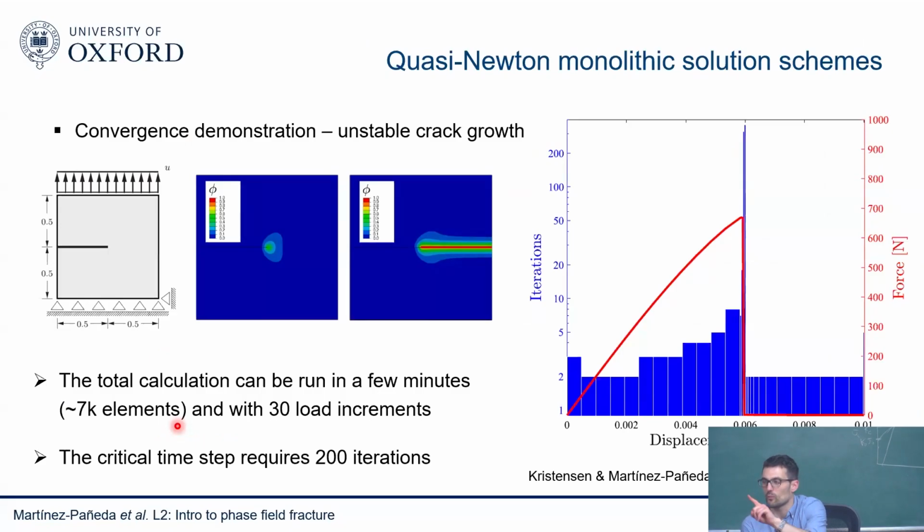One thing that came to my mind, the line search. When we started this work, we did it in Abaqus because Abaqus has it all implemented. We just touched a button and said, oh wow, this works so nicely, the BFGS. Then some people have tried since our paper to reproduce it in their own codes. I was told a few groups have managed to get this very good behavior, but you have to do it exactly as Abaqus does. So this particular BFGS implementation, and you need to put a line search, which Abaqus has already built in as well. So that's one aspect.